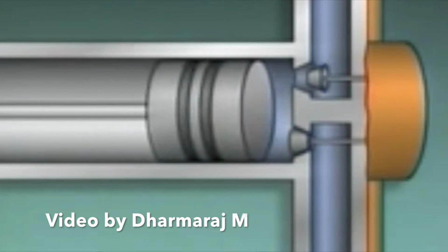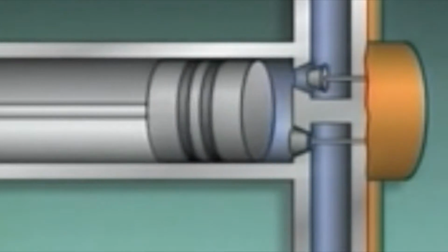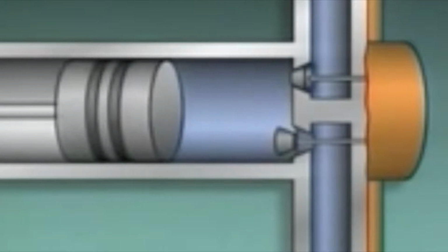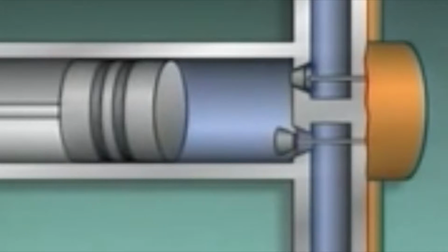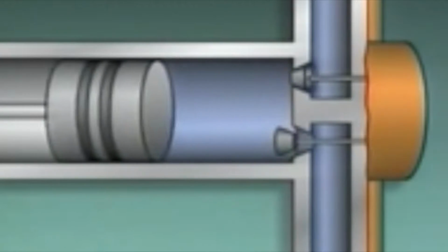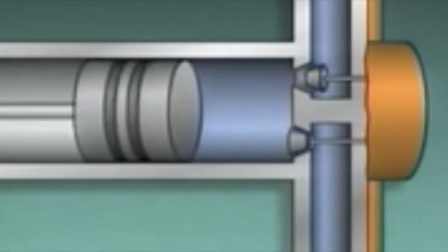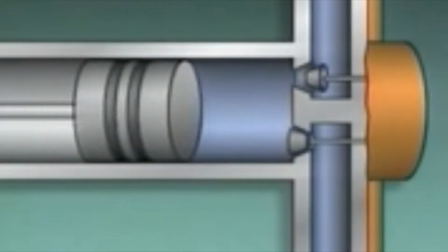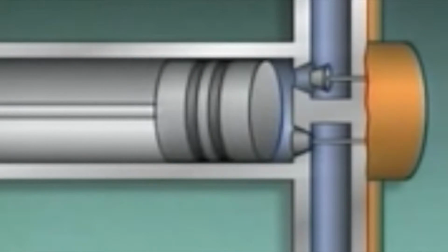This is a reciprocating pump. And what we see here is that the piston is moved backwards, causing the fluid to be drawn into the chamber, filling it up. Then the piston moves forward, causing a pressure that pushes the water out towards the top of the pipe. This mechanical pressure is what causes that consistent flow that is desired by these pumps.